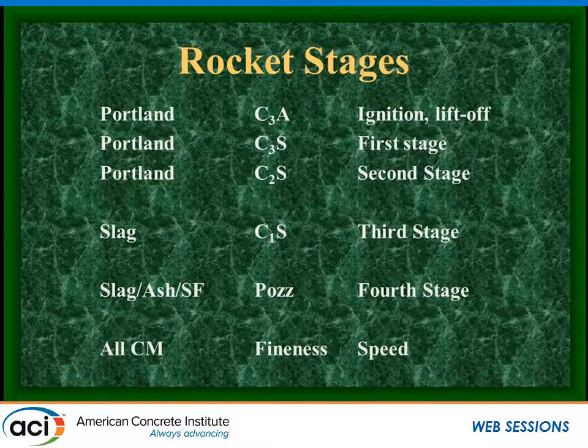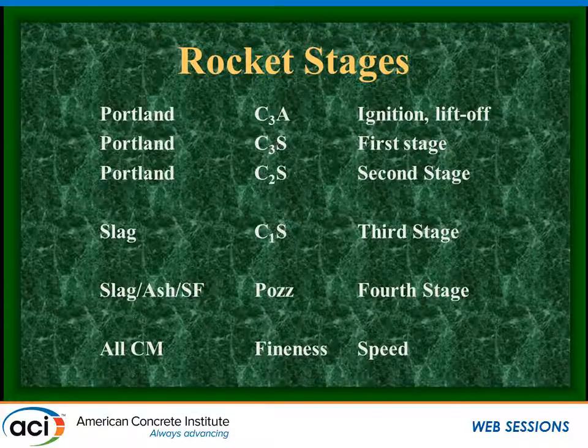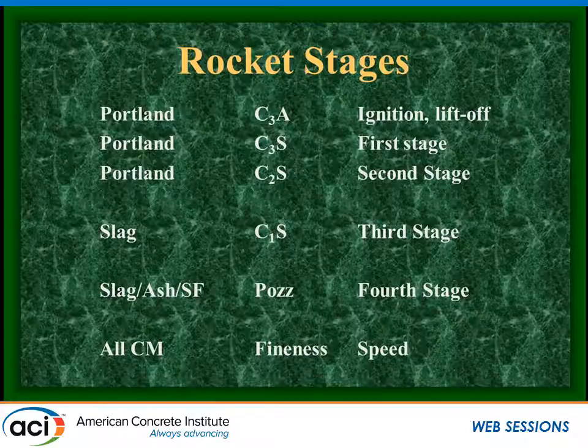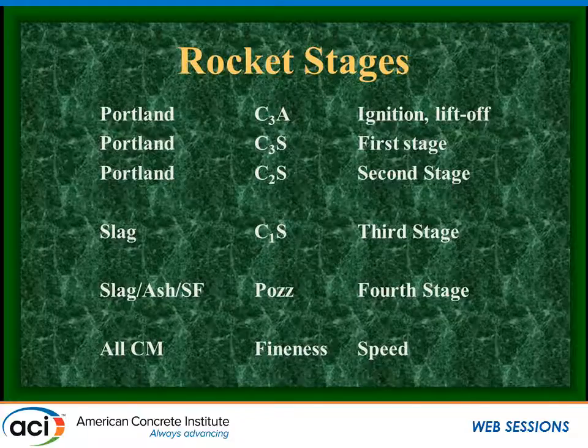Now, I try to do analogies of things that make sense to me, so I'll break down the stages of hydration. I put it kind of in rocket stages. The C3A compound, that's like our ignition. That's what gives us our first liftoff. When the water gets with that C3A, it makes heat, and that stuff wants to harden very quick. In fact, we have to use gypsum to hold it back, or the cement would take off far too fast for us to use properly in the field. That's what's just getting us off.